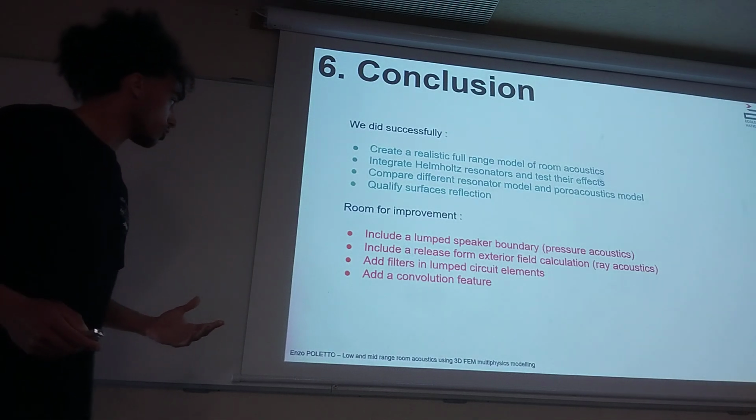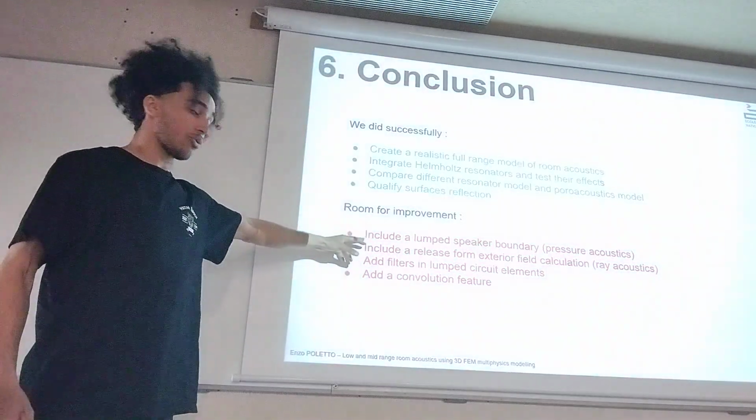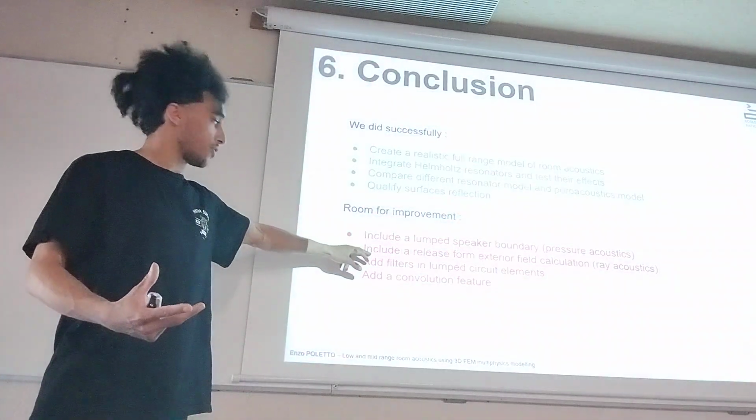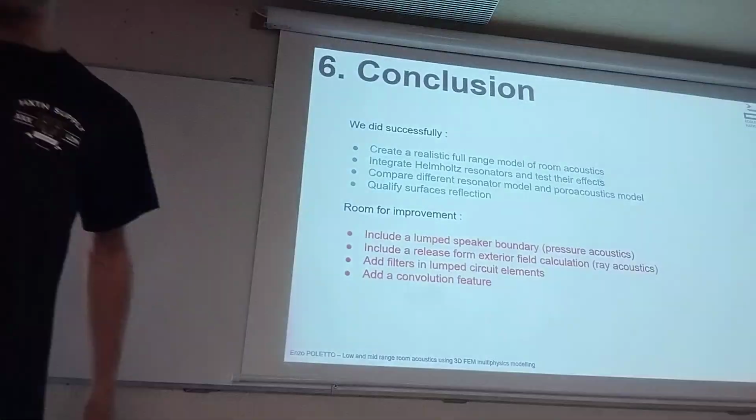And now for improvement, especially in wave acoustics, we would need to include a lumped speaker boundary, as I said. In ray acoustics, it would be from an external calculation field. We can do that directly, and eventually have filters if we want to create some more realistic speakers.